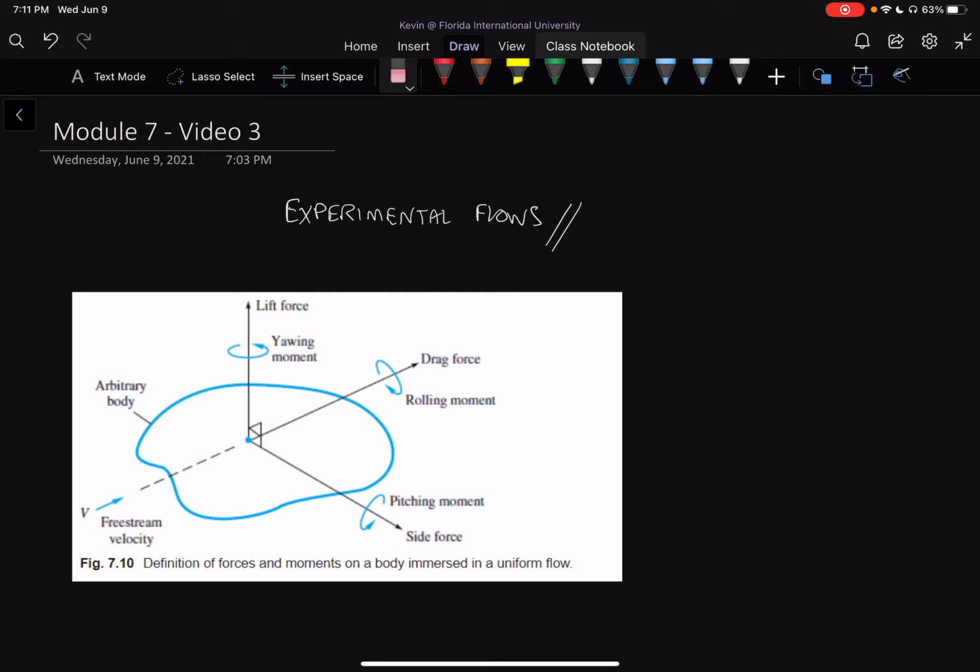Okay, so if you remember, your flow around a sphere had some flow separation once it passed the sphere. It would have a flow separation that would occur at the top and bottom of the sphere, and here we would have a very, very complex pattern to analyze. Now, our boundary layer theory cannot take that into account. So what we can say is that the theory for boundary layers is very good for slender bodies and for very, very simple geometries.